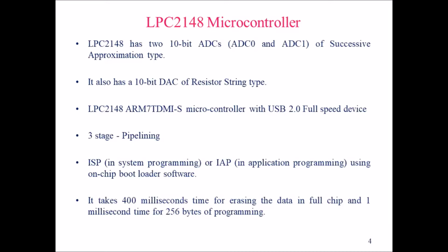So what are those three stages? The first stage is called fetch, the second stage decode, and the third stage is called execute. All the instructions which will be executed on the LPC2148 usually execute through the three-stage pipeline architecture.